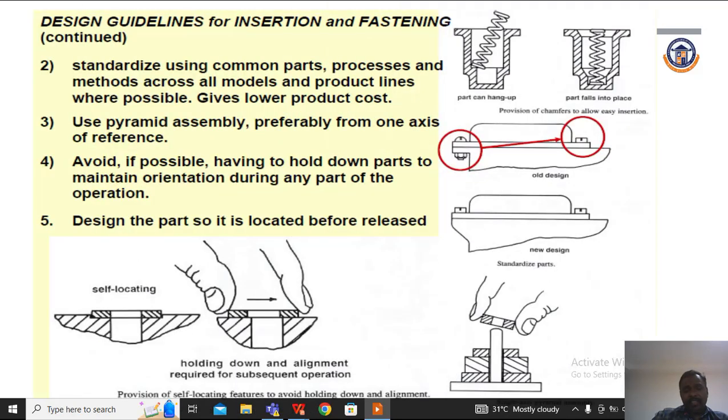And then we have some self-locking alignment for the multiple components. If you see here, there is self-locking alignment. This pin is a self-locking alignment, and here this slot is a self-locking alignment for this fastener. And here everything will be similar, that is easy to assemble.